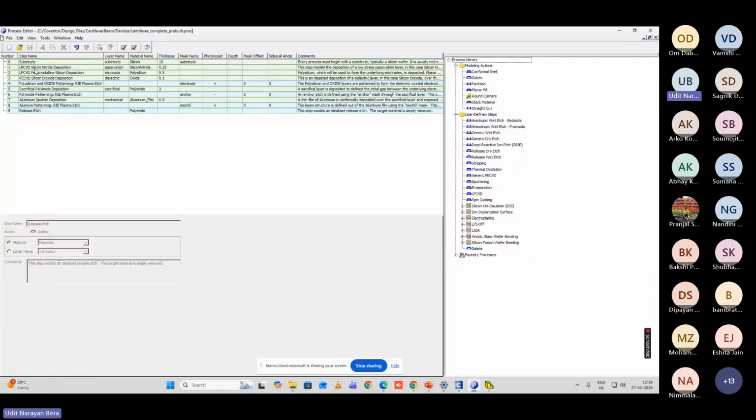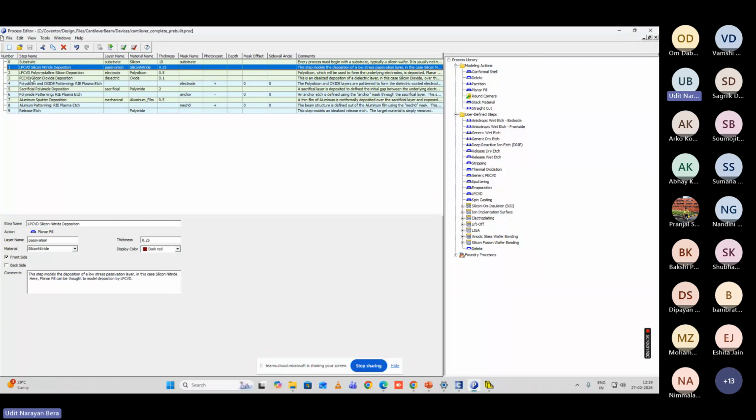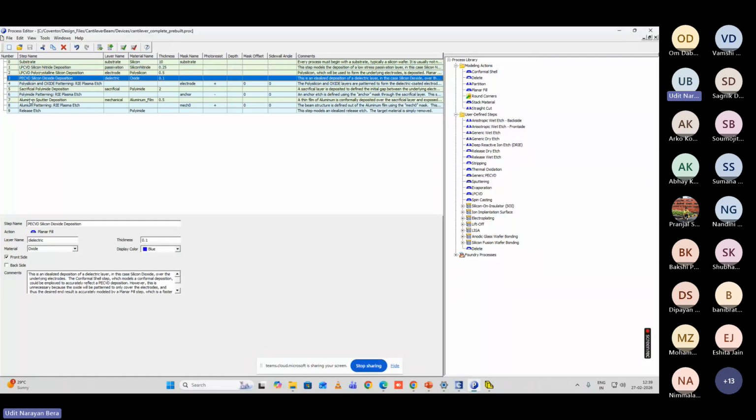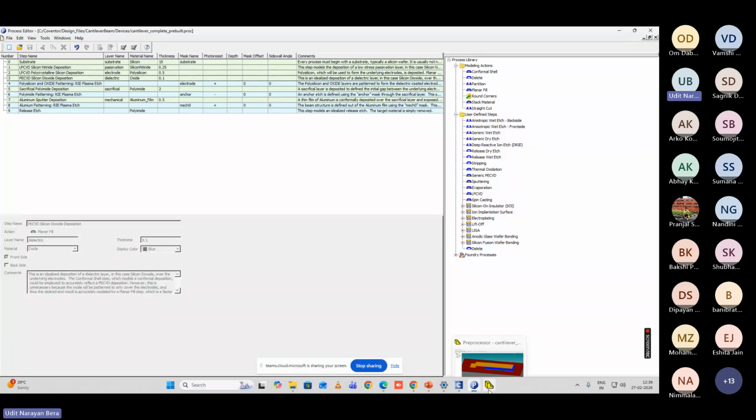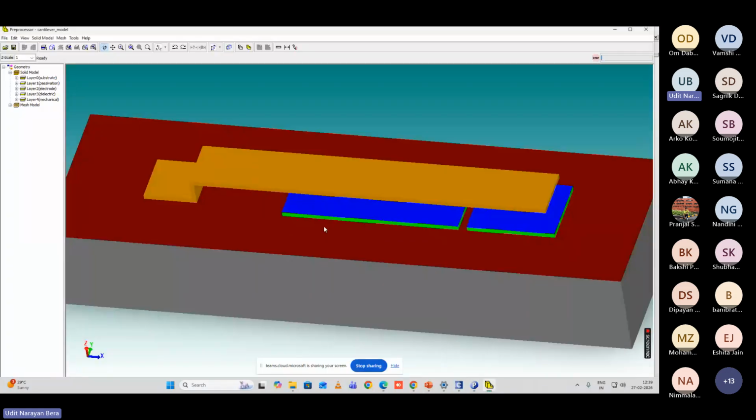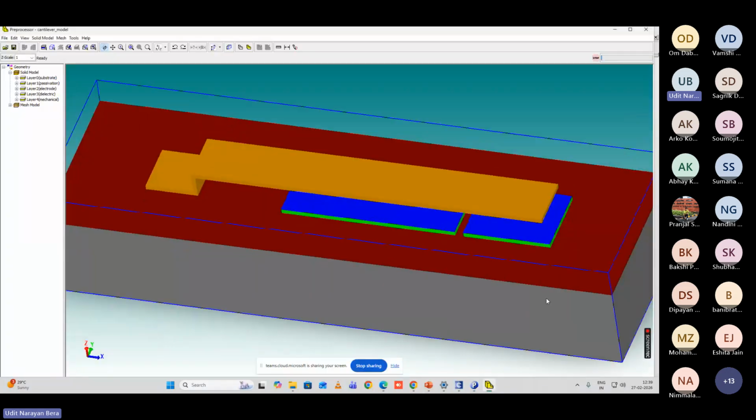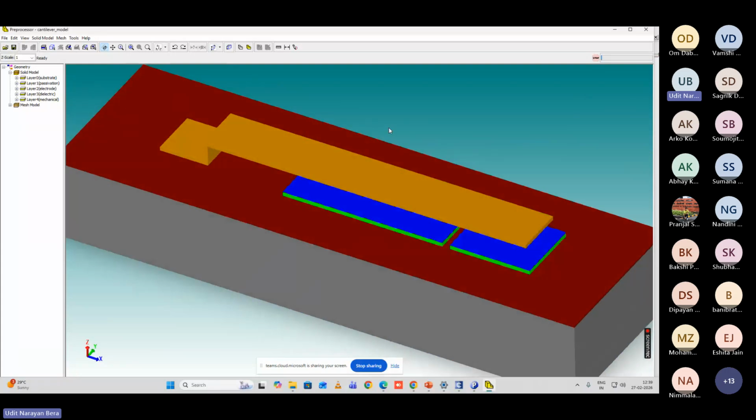You can see mainly there are CVD, PECVD, and other etching. A total of 3-4 processes have been used here. You can go through these processes in detail, but for the time being, just know that CVD and the like are all thin film deposition techniques, where you deposit thin films to make things like sensors. So here is your sensor. The sensor is built on top of the substrate.